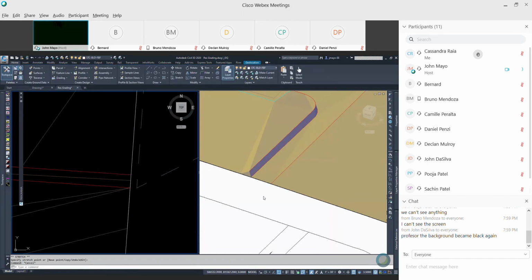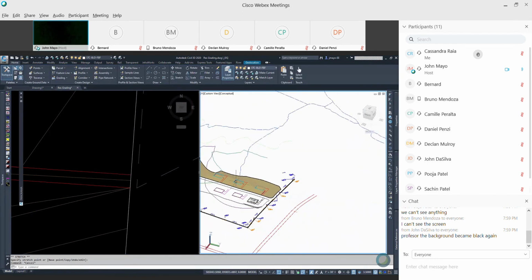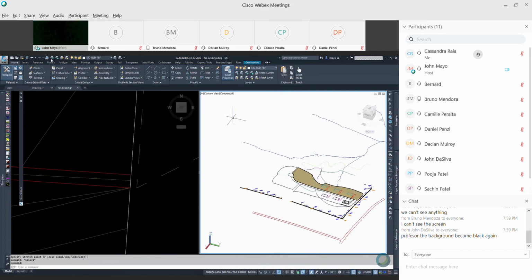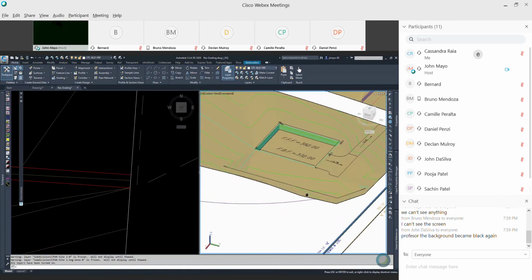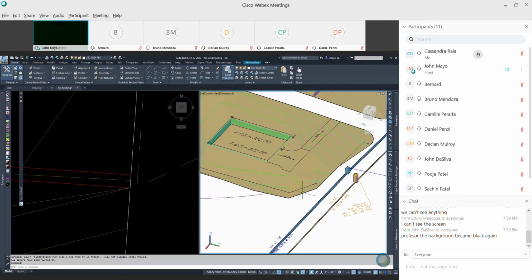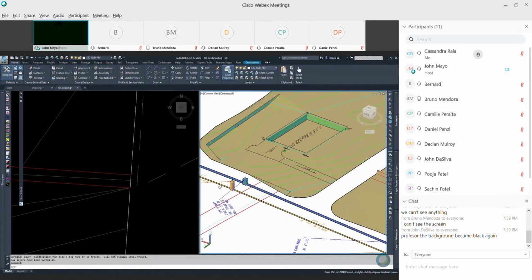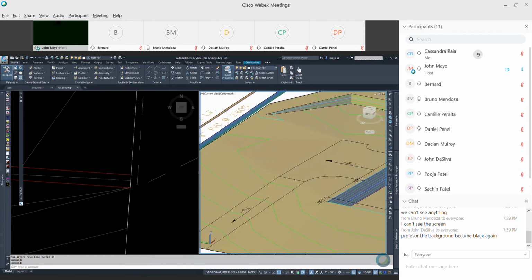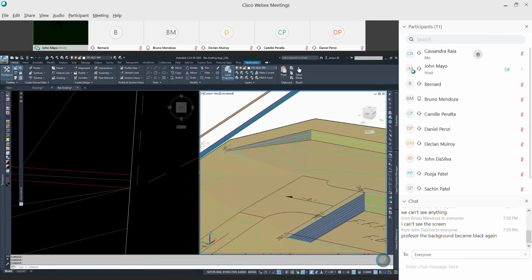Now, another thing I told you about when we talked about retaining walls, and we did talk about this last time. I'll put on my other surface and show you. We noted that retaining walls cannot really end abruptly. Can't just terminate that retaining wall with a 4-foot height like we have here.